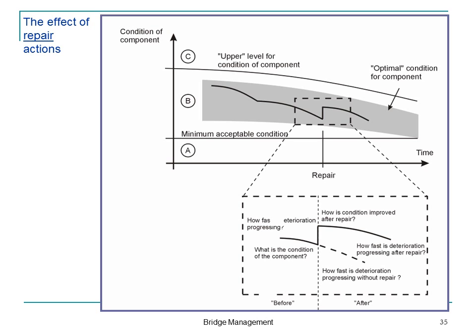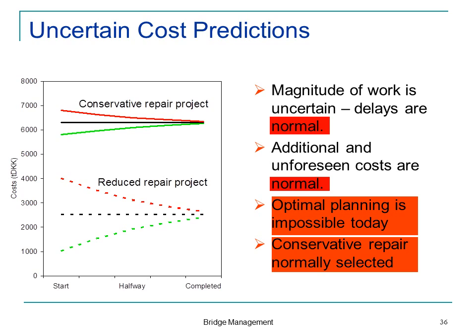And what consequences would being not quite sure have? Well, I can say logically, the ideal repair would be one where you just fix the problem. If there's a problem of, say, water penetrating through the pavement and giving frost damage underneath the pavement, or water and soil penetrating into the concrete underneath the pavement, then the proper repair would be replace the damaged concrete, replace the infected concrete.